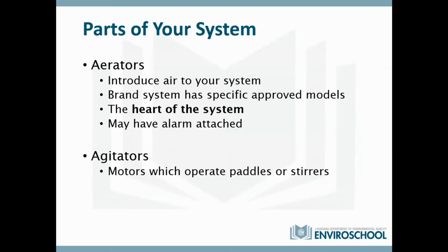With these aeration chambers, you're either going to have an aerator, which blows air into the system, or you're going to have an agitator, which operates some kind of motor that runs paddles or stirs. But the whole idea is to add oxygen to these systems. And this heart of the system just beeped. I didn't know it would do that, but the aerators are actually the heart of the system. Without the aerator or the agitator working, your system is not going to be working properly.